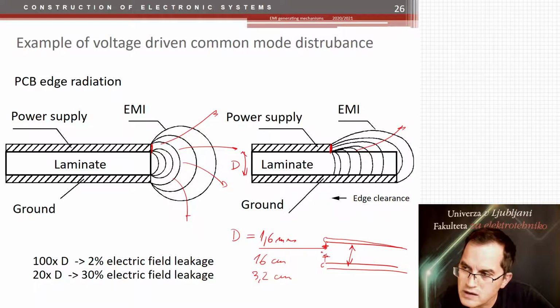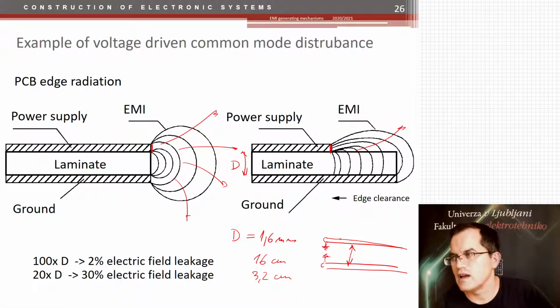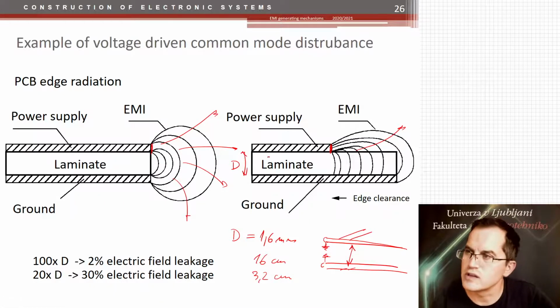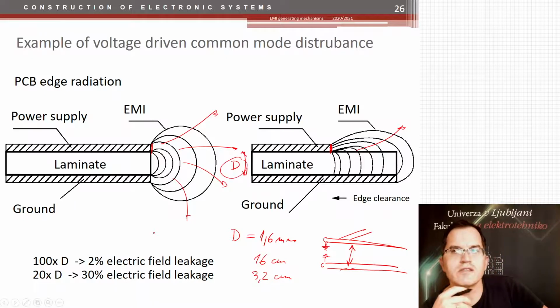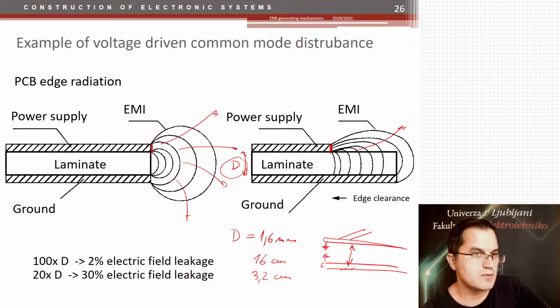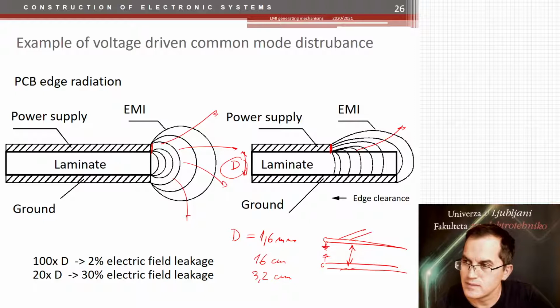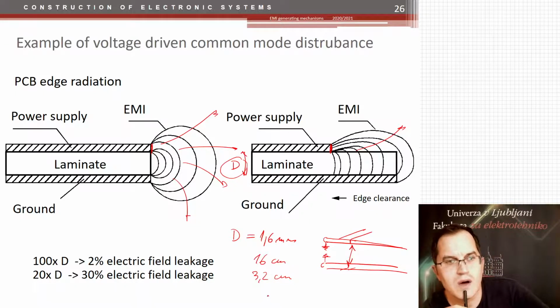And here you have ground. So now the lines on top and on bottom here are very close to the ground. So you're decreasing the thickness and therefore you're decreasing the radiation of your noise. So that's one of the reasons why these PCB stacks are like that. They do have a wide mid part and very narrow, very small distances between the two outer layers.